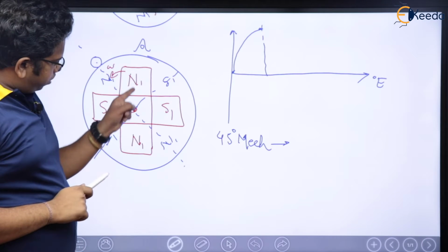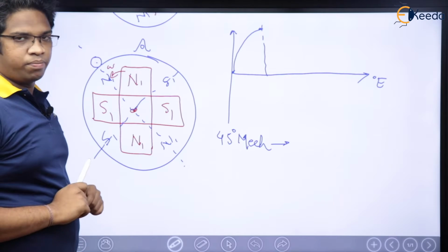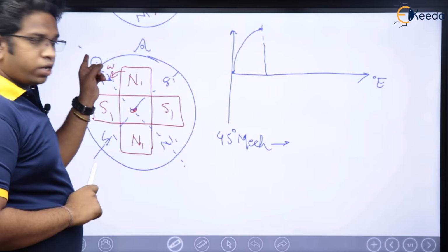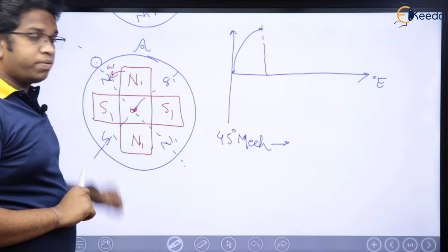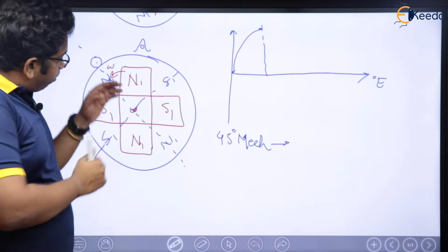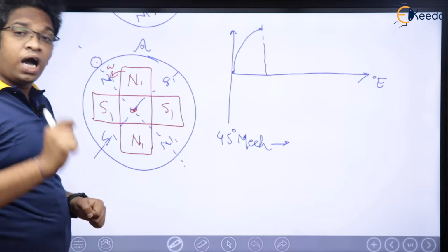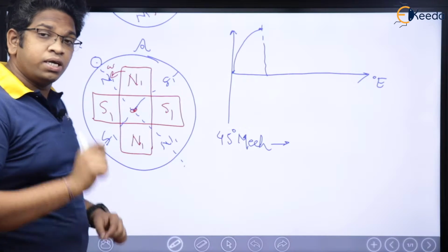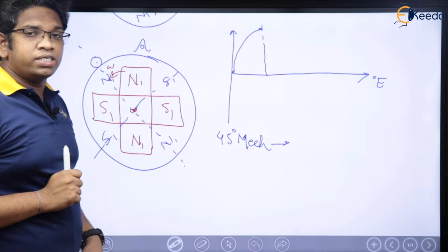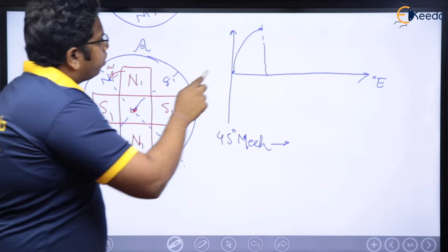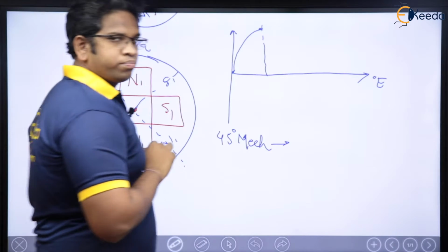This was the interpolar axis. So, as of now, the induced EMF is how much? 0. After rotation by 45 degrees mechanically, what has happened? This conductor got positive maximum voltage.